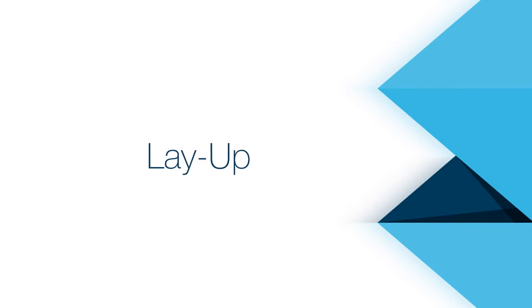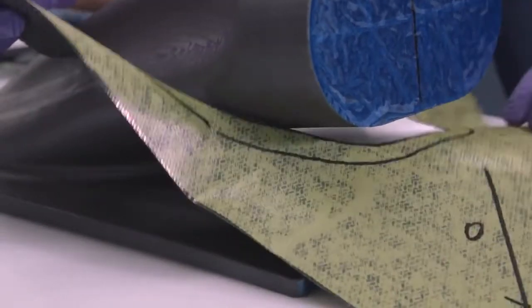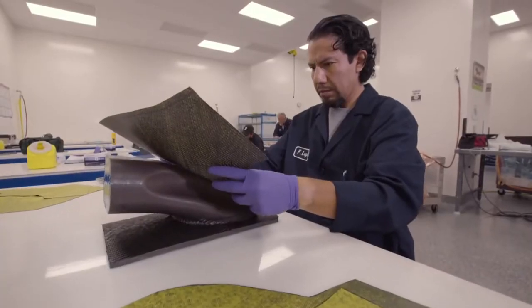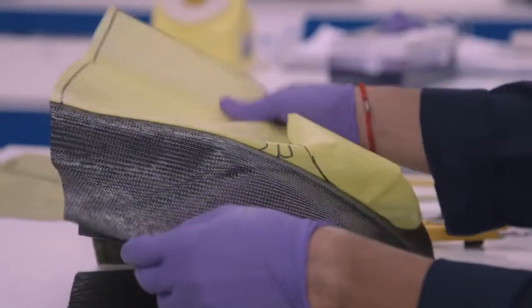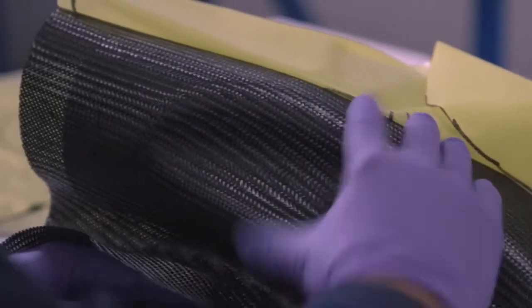The part lamination process begins with ply development, where he or she creates these patterns according to the geometries of each part. That allows the composite material to drape properly, to give the right fiber orientation, and to maintain it. That process is very tedious and very important.